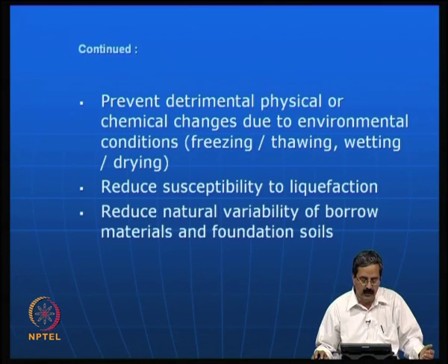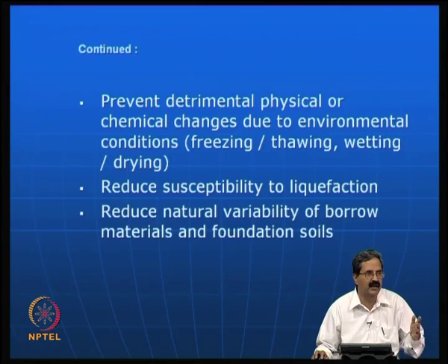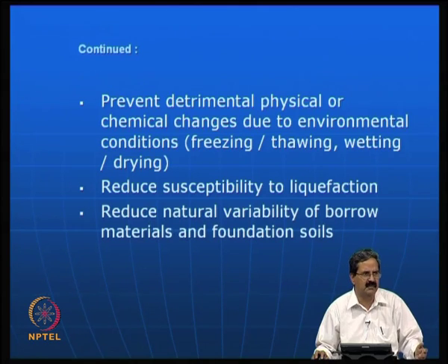Then one of the important aspects of ground improvement techniques is to reduce susceptibility to liquefaction. You do not want all the soils to get liquefied when an earthquake comes. Say for example, the Bhuj earthquake created so many problems. Many dams collapsed because of liquefaction. We have a lot of information on this, and it is a challenging problem worldwide. People have been working on liquefaction and its control: how do you avoid liquefaction, is density okay, or is a reinforcement technique okay, or is a stone column okay. Any improvement in soils will always lead to some improved liquefaction resistance.